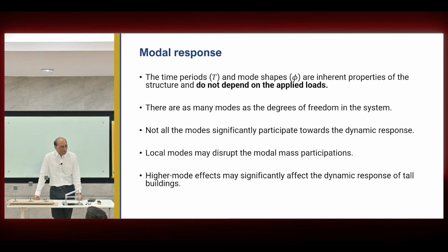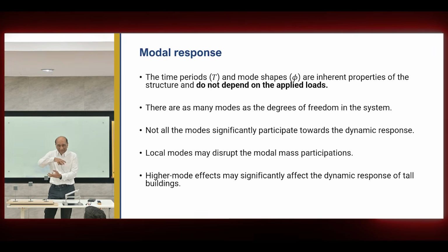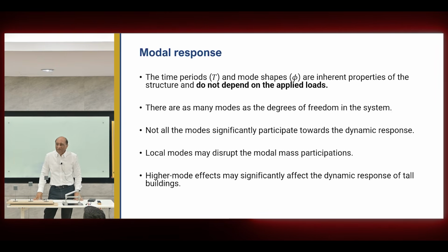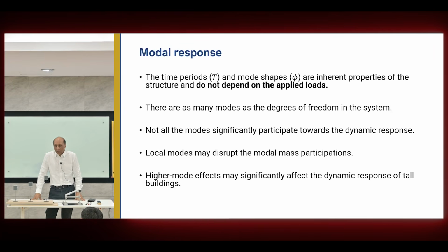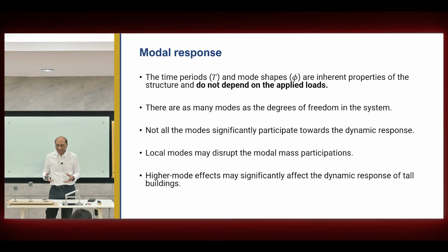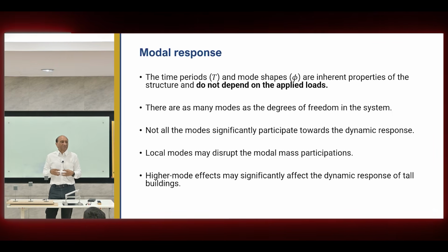The interaction surface, when we developed the interaction surface of the column, and we said, okay, this nice, beautiful color diagram of PMM is a property of the cross section, and it does not depend on any external loads. This only depends on the section definition and material. So I said the same thing, and you forgot, all of you. Good for you. I'm saying again that the natural response is the property of the structure, and does not depend on the load. Please go connect them together.